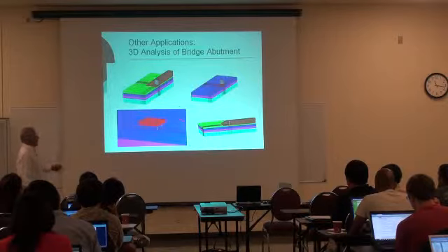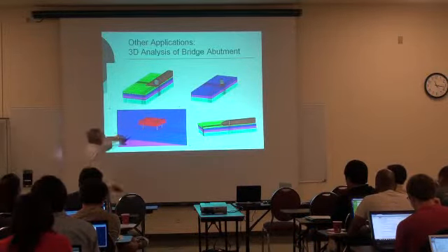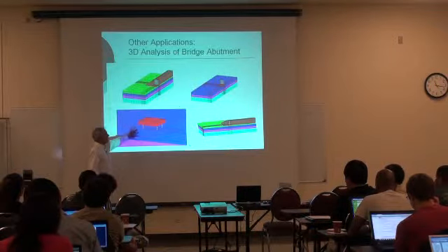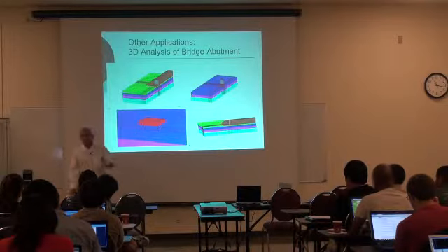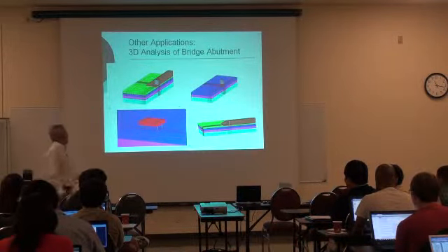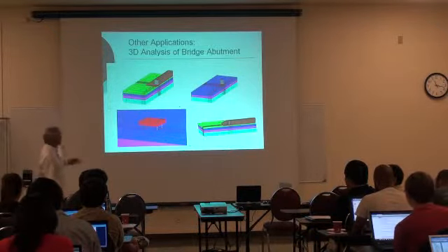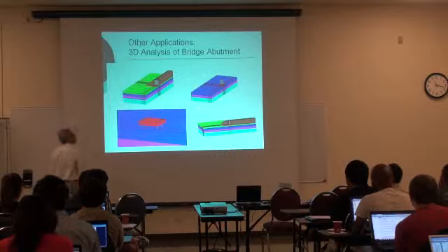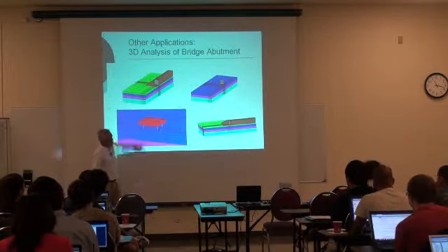I tried to run this on a conventional machine. We are using Red Hat Enterprise Linux and conventional OpenSees. It takes 7 days to run for around 400 steps. Then we switched to OpenSeesSP and the MUMPS solver. And we have seen a great improvement. This is tough to do.